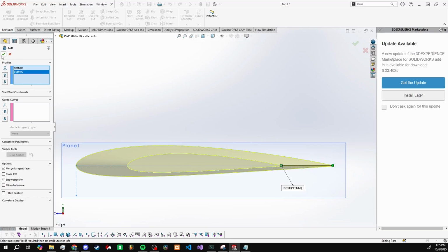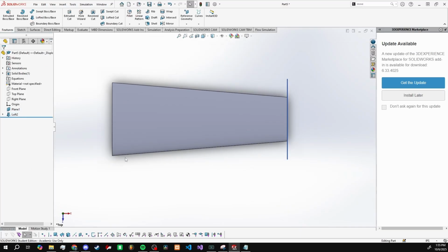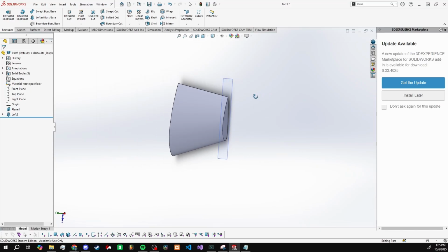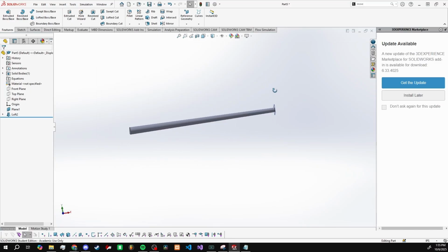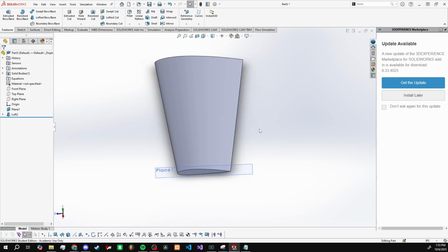And then you can see exactly how it's going to be on the aircraft. So you've got 2 inches from this leading edge to this leading edge. And then you have 2 inches from this trailing edge to this trailing edge, because we're looking at it from technically the front or the leading edge of the airfoil or the wing. So you can do the exact same thing with a forward tapered wing.